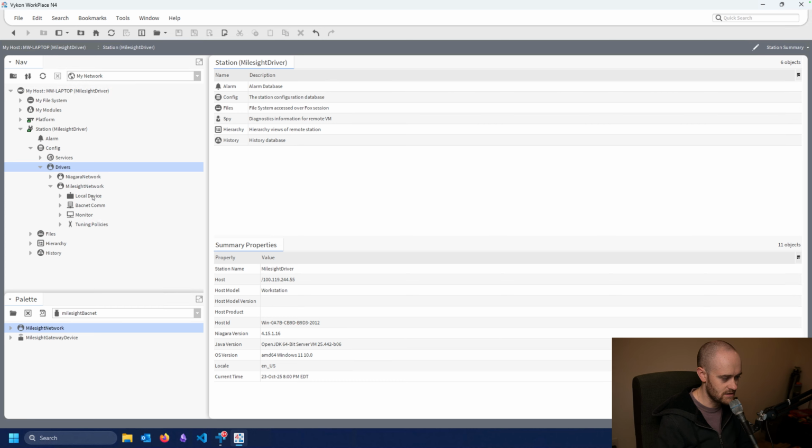So what I'm going to do is click upload here, and that's it. It automatically goes out to the gateway, pulls in all the devices that it has access to, and you'll note we have a ton more information than what BACnet was giving us directly. So we can see this is our room sensor. We can get into the points container of it. We also can see our EUI, what the codec is that we're using for the payloads, what our address is, our keys, all kinds of additional information that we don't get out of the box in BACnet.